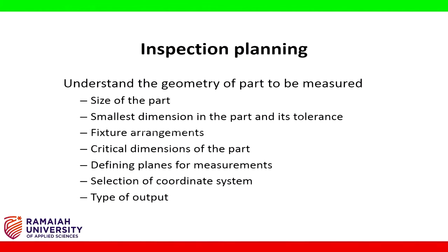Understand the geometry of the part to be measured. Size of the part. Smallest dimension in the part and its tolerance. Fixture arrangements. Critical dimensions of the part. Defining planes for measurements. Selection of coordinate system. Type of output.